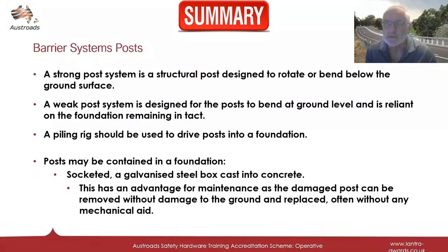A strong post system is a structural post designed to rotate or bend below the ground surface. A weak post system is designed for the post to bend at ground level and is reliant on the foundation remaining intact. A piling rig should be used to drive posts into a foundation.